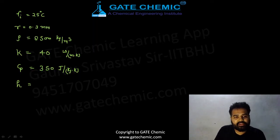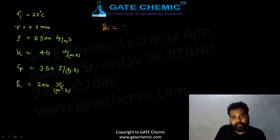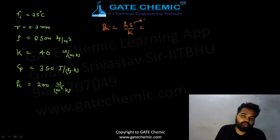Okay, h is given as 200 in SI unit, 200 watt per meter square per Kelvin. Now, this is the case in which you have a sphere of 0.3 mm radius. So first, you have to check what is the value of the Biot number here. It can be checked as hS by k. The value of S for a sphere, you know, this is volume upon area, and volume upon area you will get how much?